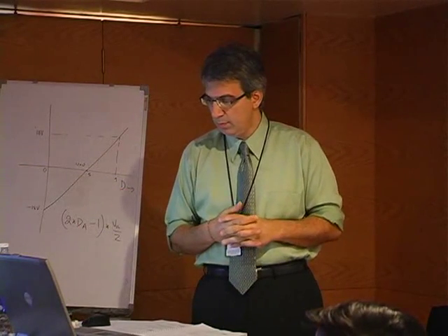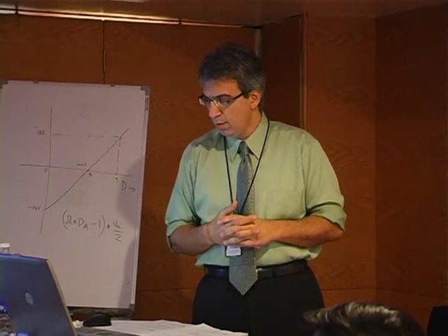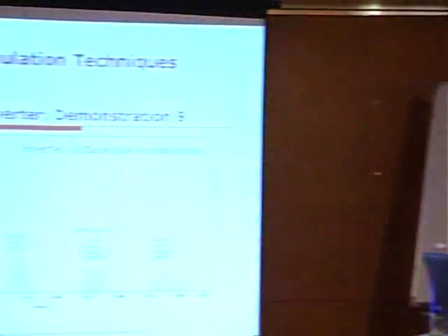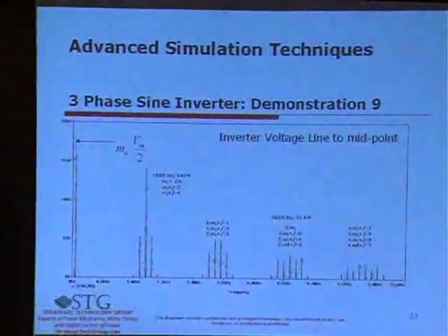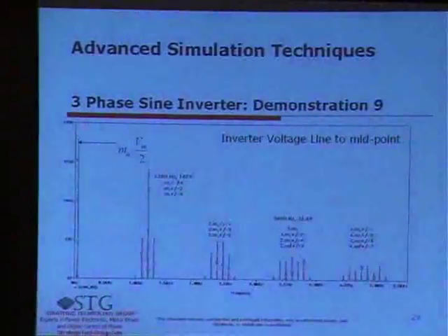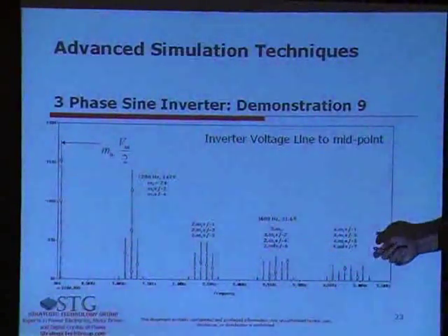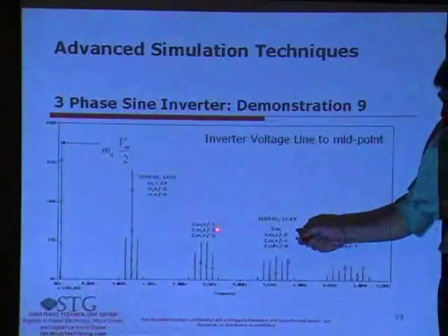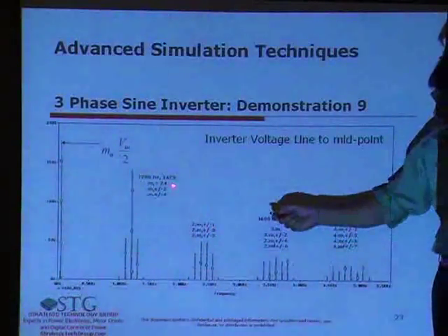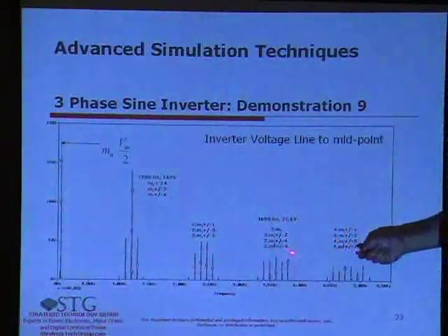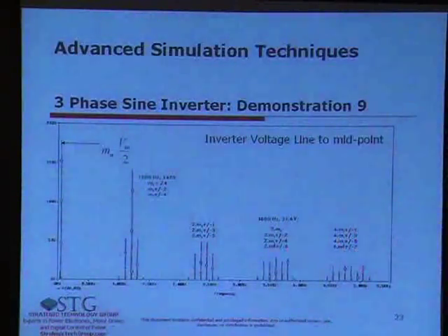MF plus minus 2, where MF, and then 2MF plus minus 1. So the interesting part here is, you have odd harmonics, 1, 3, 5. Here you have 2, 4. Here you have 2, 4, 6. Here you have 1, 3, 5, 7. So that's the theory behind this.